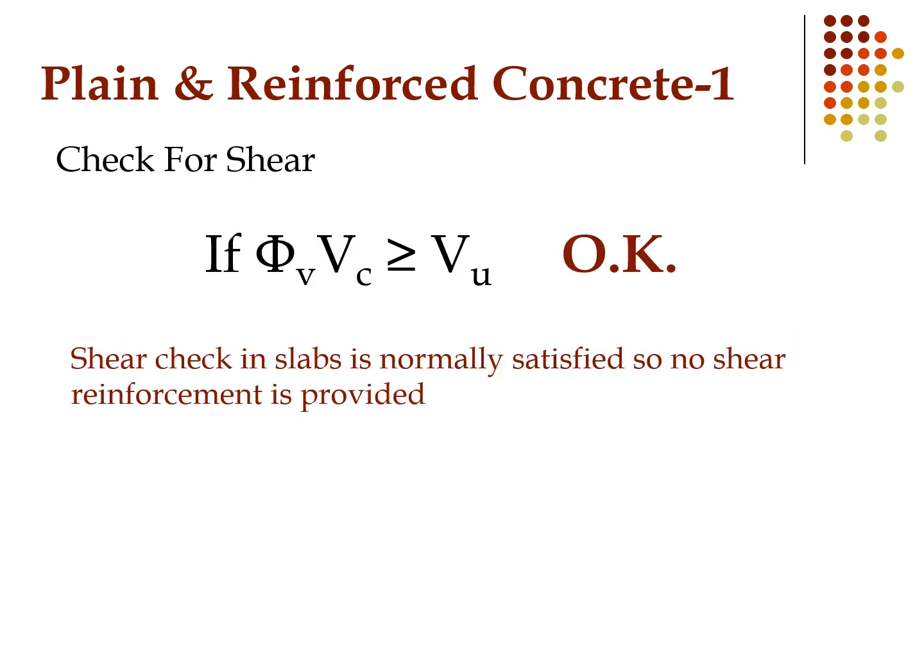The minimum thickness for the slab is normally 100 millimeter for normal slabs, and depending on the loading condition we can go up to 9 inch. There is no hard and fast rule, but in residential buildings we normally provide 6 inches. Again, it depends on the design and calculation.